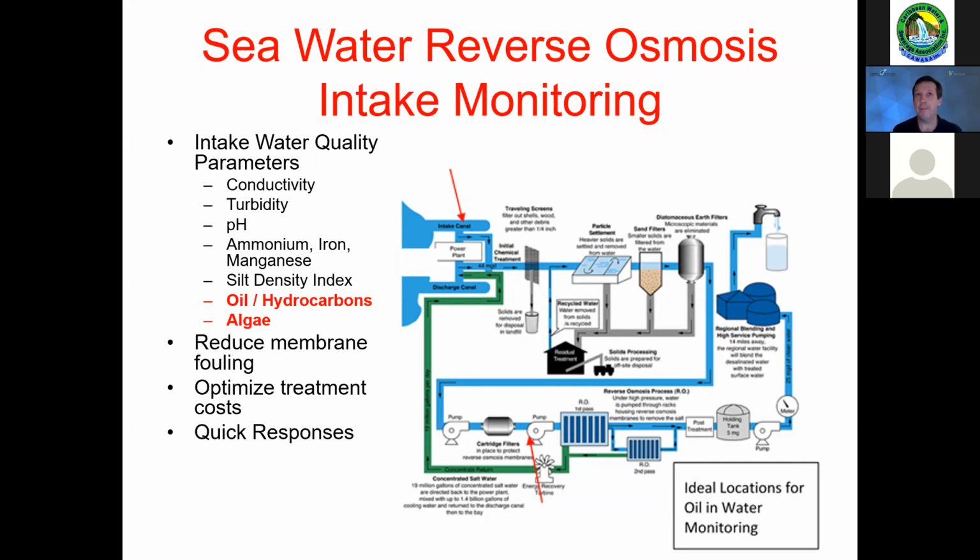What will happen after damage is that more salt will pass through the system, more dissolved solids. Calcium and sodium and all those kinds of things will pass through the membranes when they wouldn't otherwise. So your production is no longer fresh water. It has a little more salt in it than what you wanted. And the only way to fix this is replacement of the membranes.